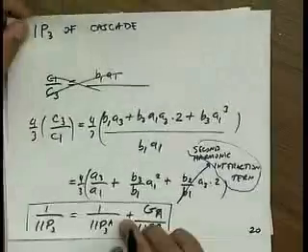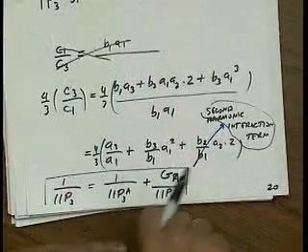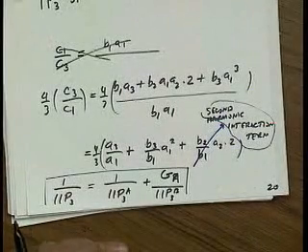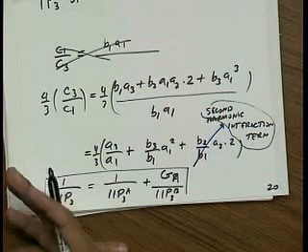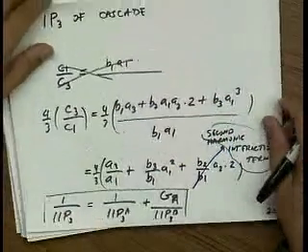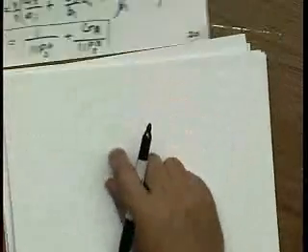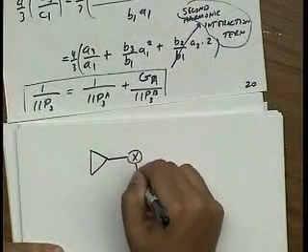Okay, so coming back to this input IP3, the exact same calculation that we did for IP2 also applies to IP3. Usually you get into situations where the IP3 of one device will dominate. So for instance, if I have an LNA and a mixer, we haven't talked about mixers yet, but a very common combination is LNA driving a mixer.